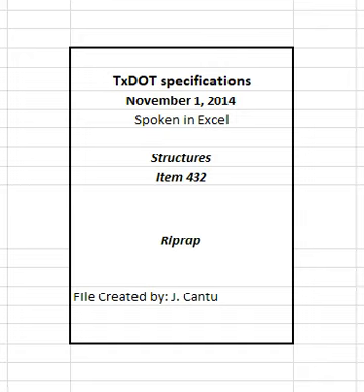3.2.1 Type R. Construct riprap as shown in Figure 1 on the stone riprap standard and as shown on the plans. Place stones in a single layer with close joints so most of their weight is carried by the earth and not the adjacent stones. Place the upright axis of the stones at an angle of approximately 90 degrees to the embankment slope. Place each course from the bottom of the embankment upward with the larger stones in the lower courses. Fill open joints between stones with spalls.